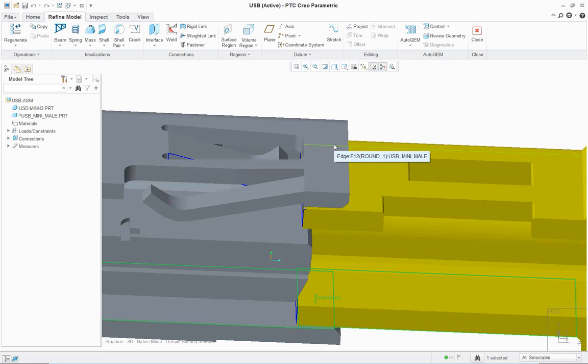Now, there's another question here about the friction of the materials. Typically you would find that on the material specs. Now, you asked how accurate it has to be in order to type in those values there. Technically, it doesn't have to be super accurate. If you know the friction coefficient is going to be 0.25, then you can type in 0.25 in there.